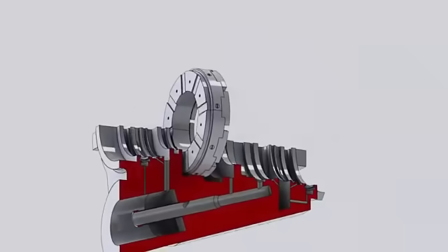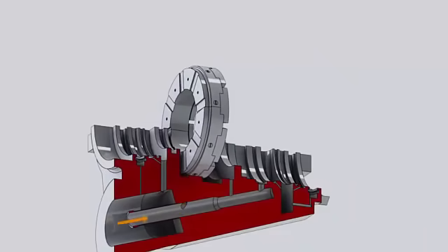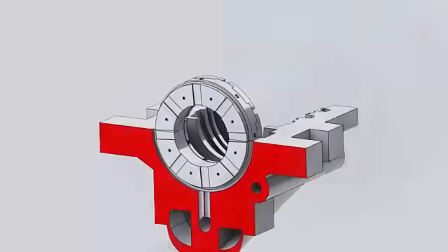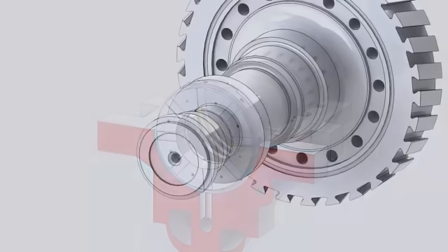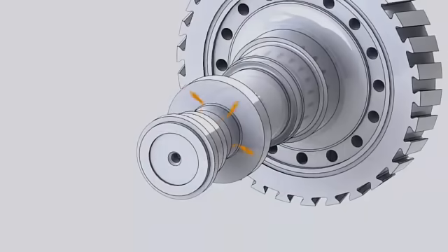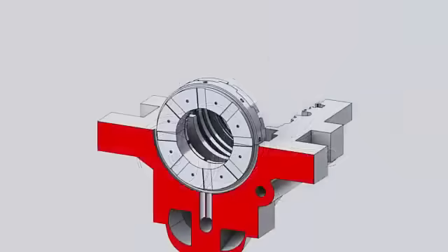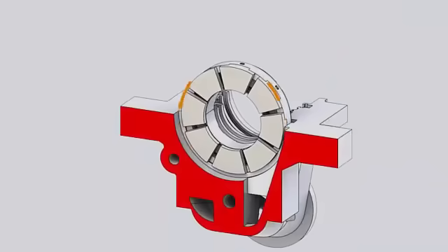For lubrication, oil is supplied through the oil feed pipe to 2 ports in the lower bearing housing, where the oil flows into annular space around the base ring. Then, oil flows through grooves machined on the back side of the base ring to the bearing cavity, where it is carried by the pumping action of the thrust runner to the entire bearing surfaces. Oil exits at the pad's periphery to the thrust bearing drain cavity down to the lube oil drain piping.